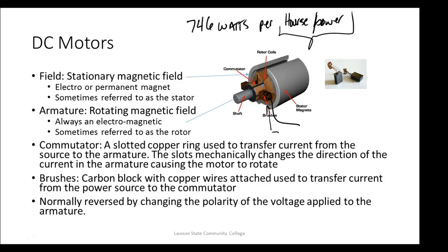Now it's got oil on your brushes, so being real hard, they become soft. They wear out, and as soon as they wear out, they get into the commutator and tear the commutator apart. And now what can you do? Go out and buy a new one, right? So yeah, if you tear up that commutator, you got really big problems.